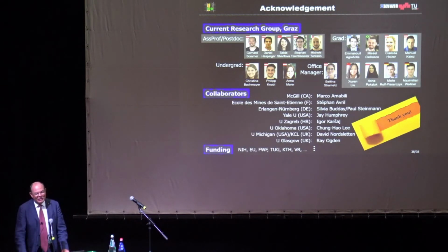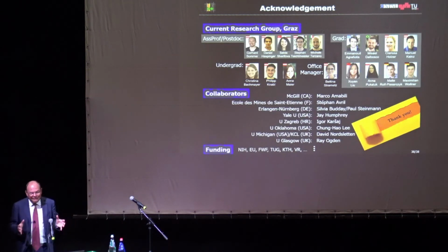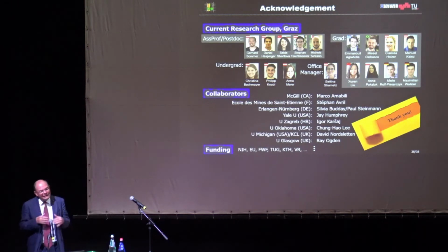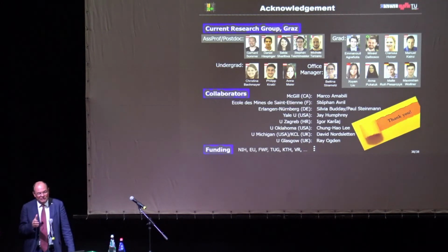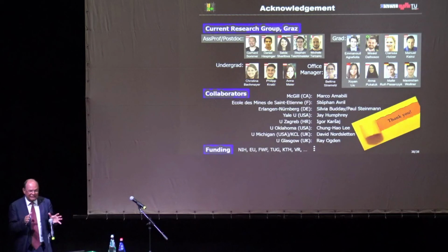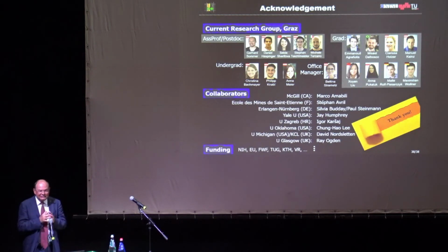That's a good point. We are all engineers, and we have to understand what is a main contribution to that what I want to model. If you model everything, what mathematicians sometimes want to do, then you are lost. So we have to figure out what is the effect I really want to understand. And I think for the wall, it's important to model it as nonlinear, because still people are doing a Hookean material, which is not possible, and do it anisotropic. If there is dispersion or not, this is maybe a detail. This is maybe not important. Take my 2000 model, for example, that's enough. So that's a first attempt, and that's it.